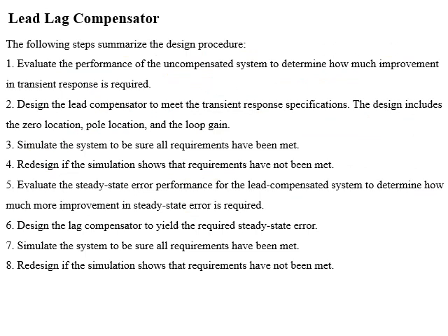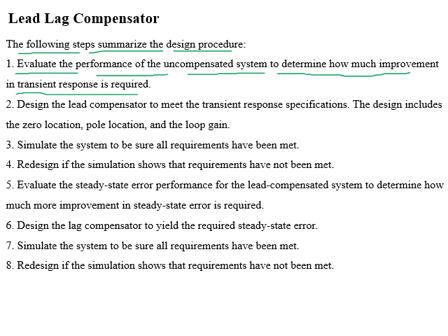Dear students, the following steps summarize the design procedure of lead lag compensator. At first, we will evaluate the performance of uncompensated system to determine how much improvement in the transient response is required. After this, we will design a lead compensator to meet the transient response specification.